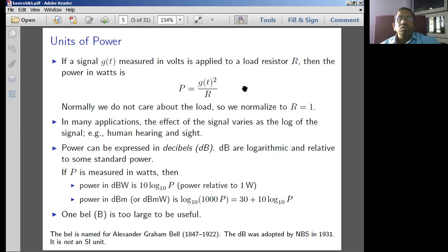Now P is equal to what I can write as? I can write P is equal to I square R, V square by R. Two equations we can write. So P is equal to V into I. V can be written in terms of I as V is equal to IR. Basic formula for V is equal to what? Voltage drop is equal to I into R. So when I write in the equation for power, P is equal to I into R for V, then I can have I square R. Similarly, I can have V square by R for the power relationship.